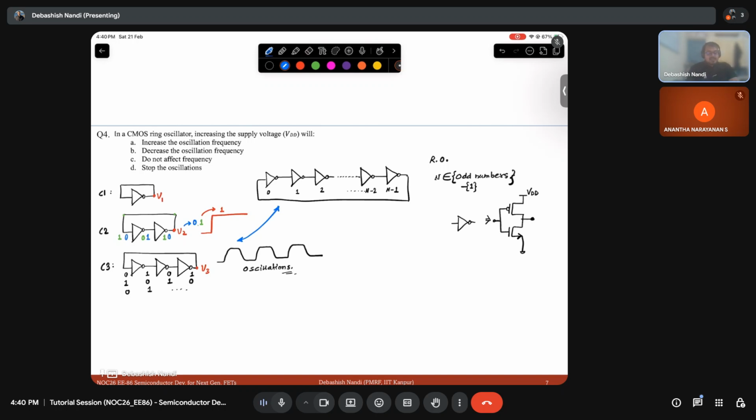So this case you read, this case also you read, and this case, believe me, will be asked in your interviews. What is the output of this case? So won't it just be the inverse of the input? But input and output are connected, right? So it won't be like 0, 1, then 1, 0. That is where we'll come to how this inverter, how the ring oscillator operates.